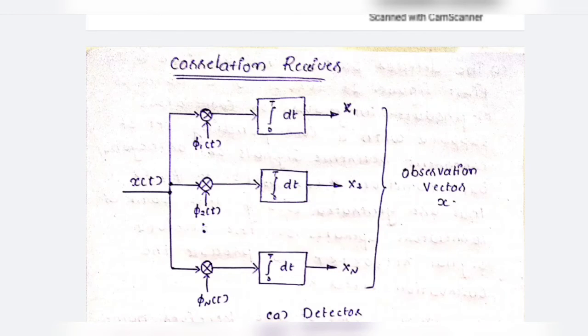Next topic is correlation receiver. It's a radio astronomy receiver in which either the noise power from a single antenna is split and multiplied with itself, or the noise power from the two arms of an interferometer are multiplied together. Signals that are uncorrelated, that is completely unrelated, give an output whose average value is 0 when multiplied together.